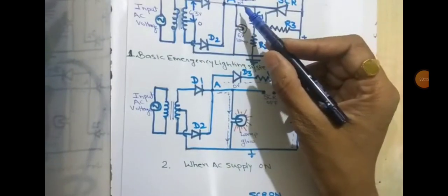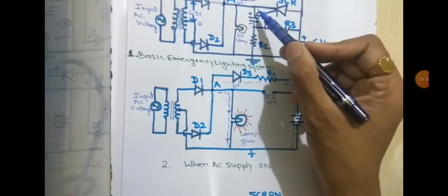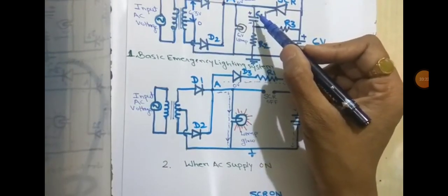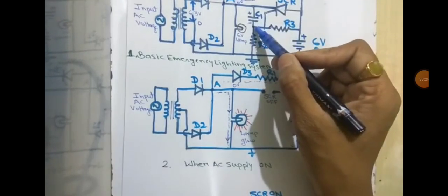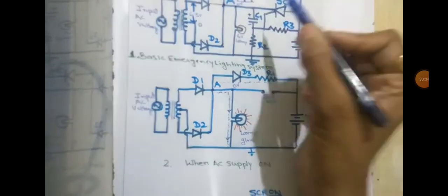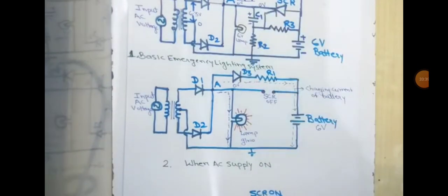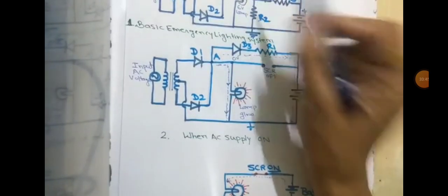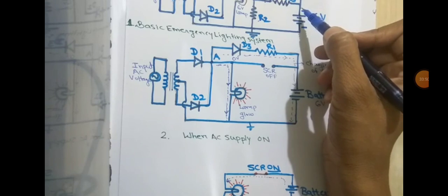Because of this reason, the cathode potential is changed, and the voltage across the capacitor is also changed. Capacitor C1 is discharged through the upper plate positive, diode D3, R1 and R3, and the lower plate of the capacitor which is negative. Because of this reason the cathode potential is dropped down to 0 volts, and hence the anode potential is higher than the cathode.